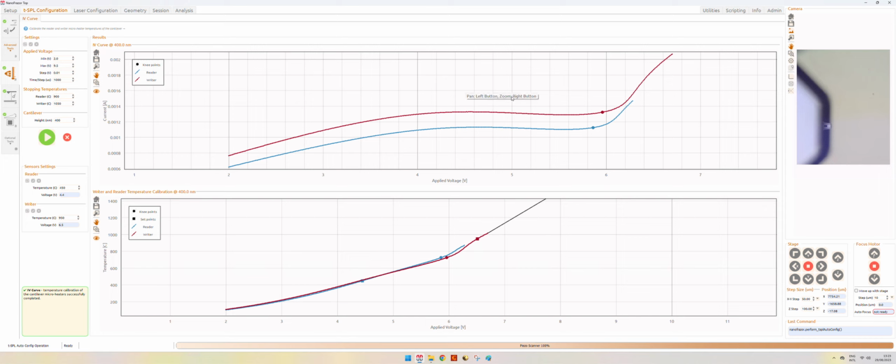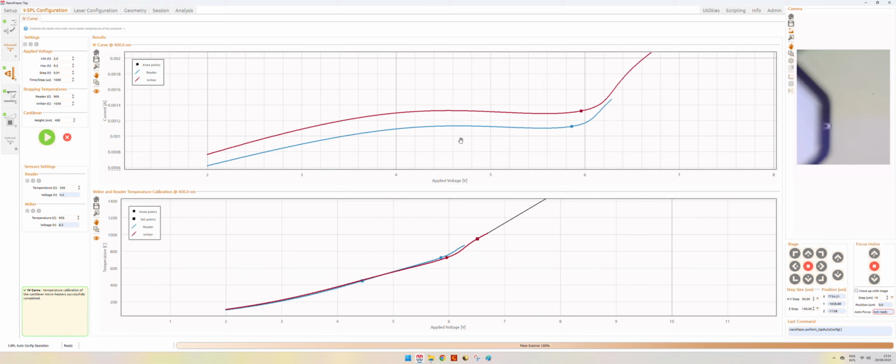As you can see here, we have two curves because we have two resistances, and these two curves are different because these are two regions of the cantilevers which are differently doped. The material is silicon, so the behavior of this curve will resemble that of an IV response of a doped semiconductor. In general, since we have different doping levels, we should not expect these two curves to match, and they should pretty much always look like this, because in case the material is not ruined, this is a typical behavior of doped semiconductors.